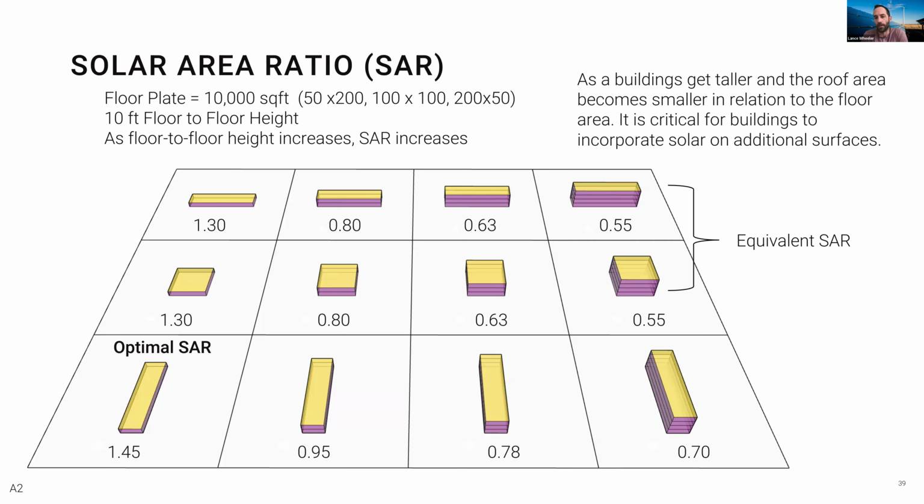And just to pivot into another question, which was, has anybody conducted techno-economic analysis of BIPV applications? I'll definitely let Chris and Stan take this one as well. But from a window or a glass perspective, where glass is a cladding material, the current state of PV is that glass, and this is true for thin film and for silicon, is the most expensive and most carbon intensive piece of that panel. So if you're thinking about saving money and saving carbon, if you can dual use your glass by making it both photovoltaic and a piece of your facade, it makes a lot of sense just intuitively.